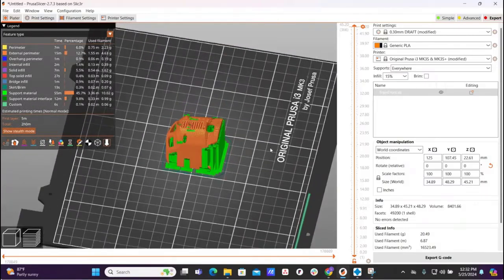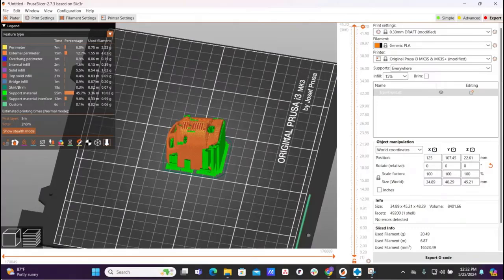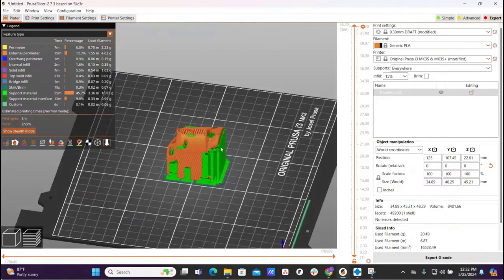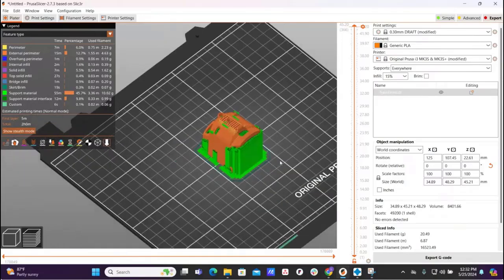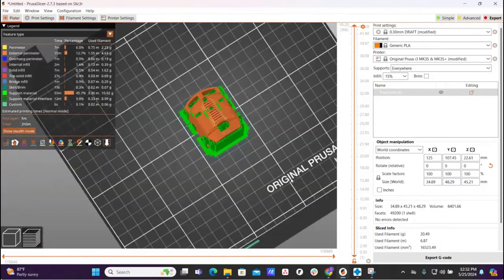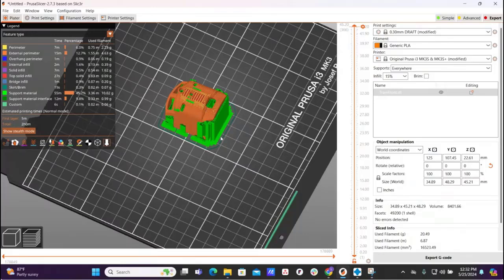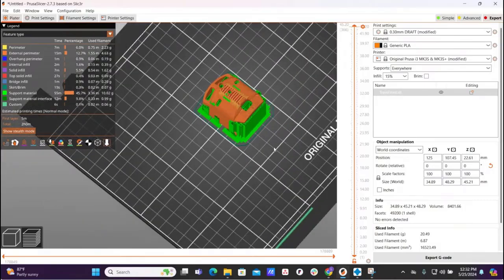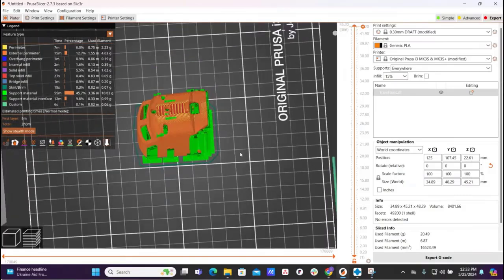So in our settings, we have ways to control quality. We have ways to control all the settings for the time it takes to print, the temperatures for the filament to avoid stringing, supports to make sure everything comes out as expected. So these are all things that you have to be mindful of. And when you're pulling these supports away, you're going to have some little things that you may have to clean up as well, like these little pock marks on the surface, or bumps or things that you'll have to remove. So just something to keep in mind.